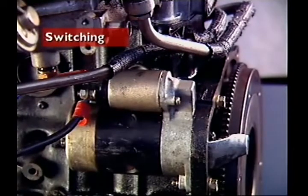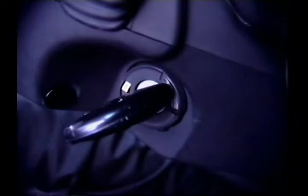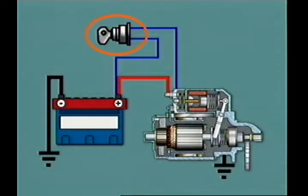This section examines starter motor switching. The starter motor is usually brought into operation by activating a starter switch as part of ignition key operation. This remote control operates a starter-mounted solenoid which has two functions. It acts as a solenoid to engage the pinion with the flywheel ring gear, and it acts as a relay to bridge the main starting terminals.